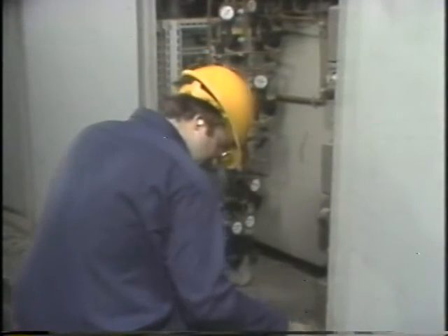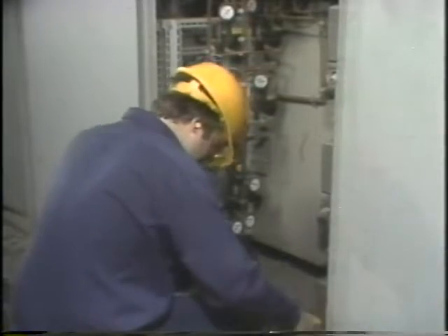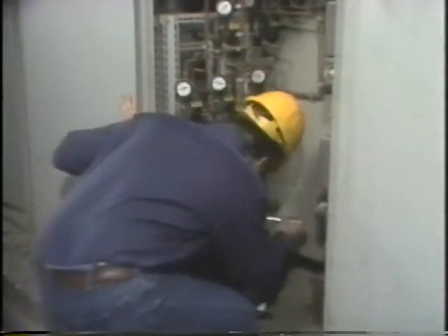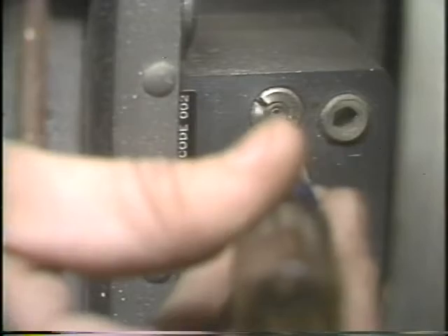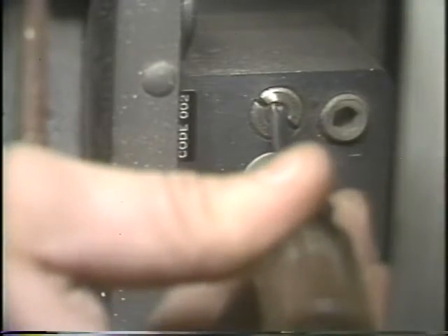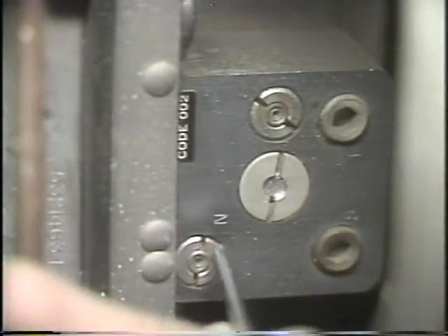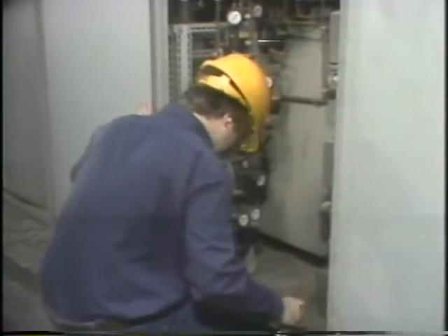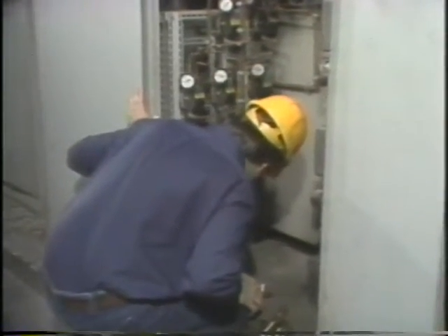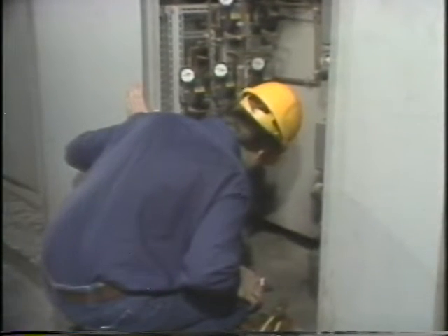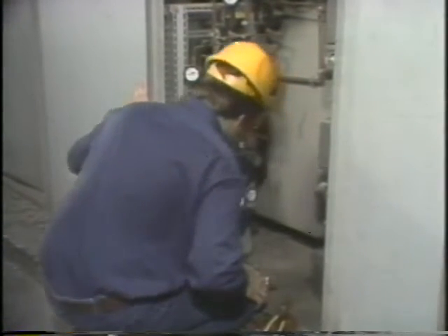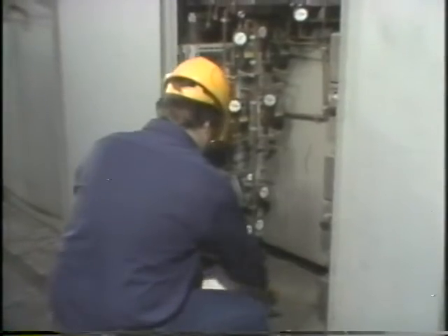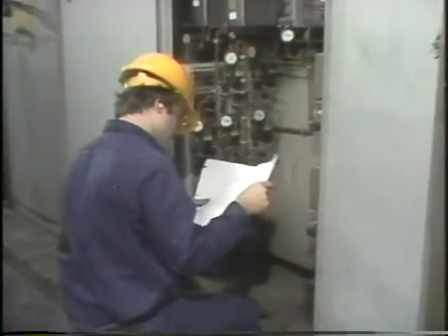The settings are about where they should be. This controller's got a booster relay too. I'll go ahead and punch the orifices out while I'm here. That's one. Let me get the other. There. Yeah, it's not affecting its output at all. This controller was working in automatic too, just like the ratio controller.